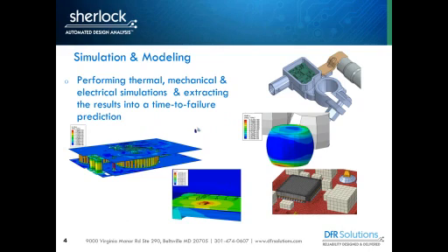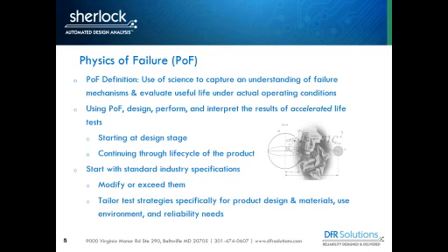You can develop very detailed models, but if you don't know what those results mean in terms of reliability, you're kind of missing out. So it's really very important to know what types of stress levels copper vias can take, what types of temperatures your components can withstand, and what types of stresses and strains your solder joints can tolerate and still provide a robust electrical interconnection.